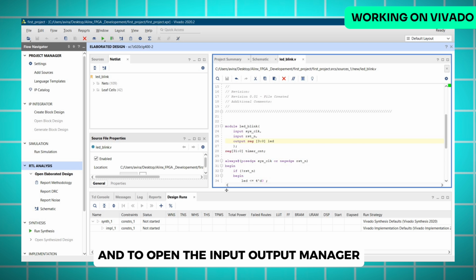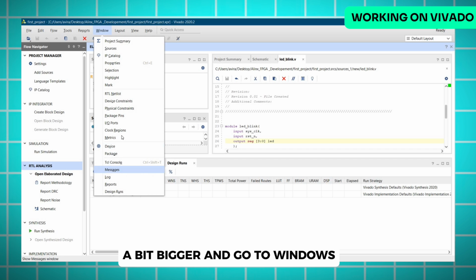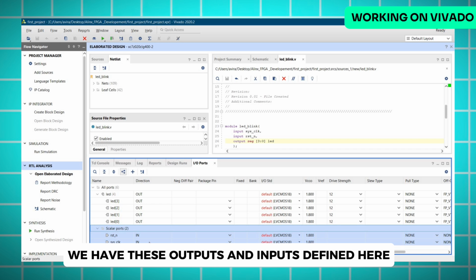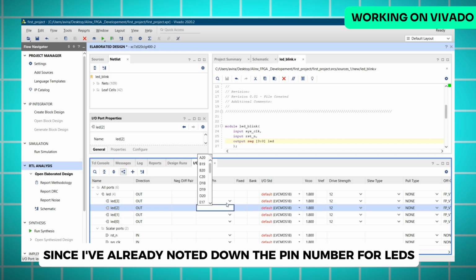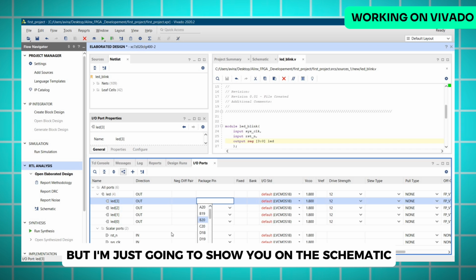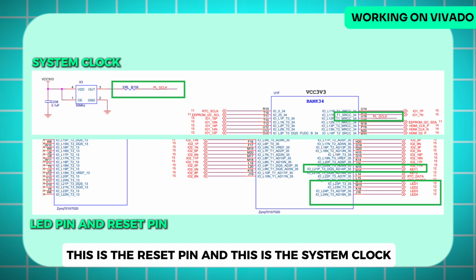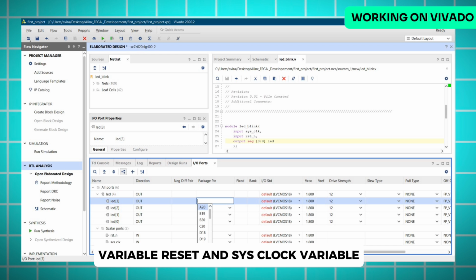And to open the input output manager, we'll just make this window a bit bigger and go to Windows. And from here we have to select IO ports. Alright, let's expand these. So here you can see we have these outputs and inputs defined here, and from here we can assign the pins. So if you remember the schematic, since I've already noted down the pin number for LEDs, reset and sys clock, but I'm just going to show you on the schematic one more time on your screen. So as you can see, these are all the LED pins. This is the reset pin and this is the system clock from the schematic. We are going to assign these LED0 to LED3 variable, reset and sys clock variable.